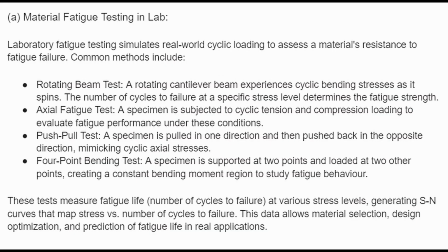A. Material fatigue testing in the lab. Laboratory fatigue testing simulates real-world cyclic loading to assess a material's resistance to fatigue failure. Common methods include A. Rotating beam test. A rotating cantilever beam experiences cyclic bending stresses as it spins. The number of cycles to failure at a specific stress level determines the fatigue strength.